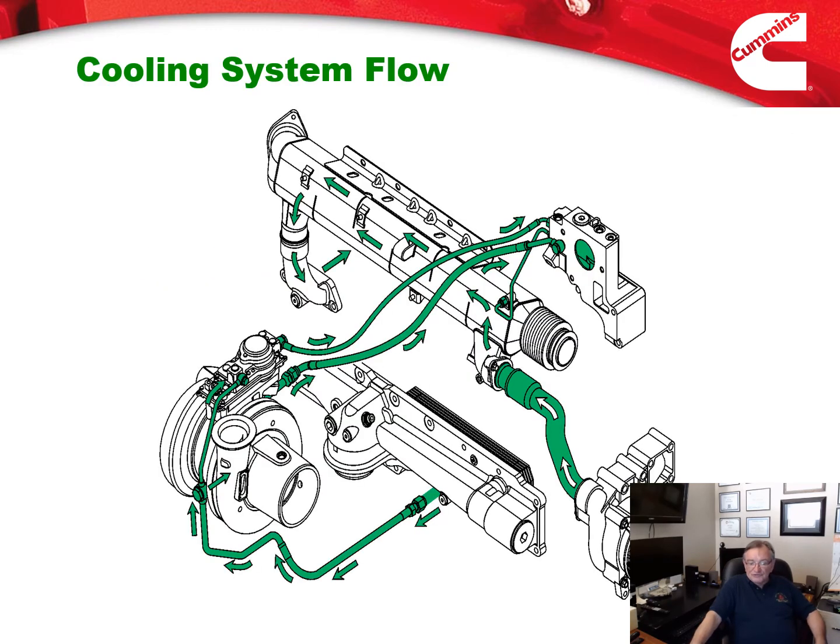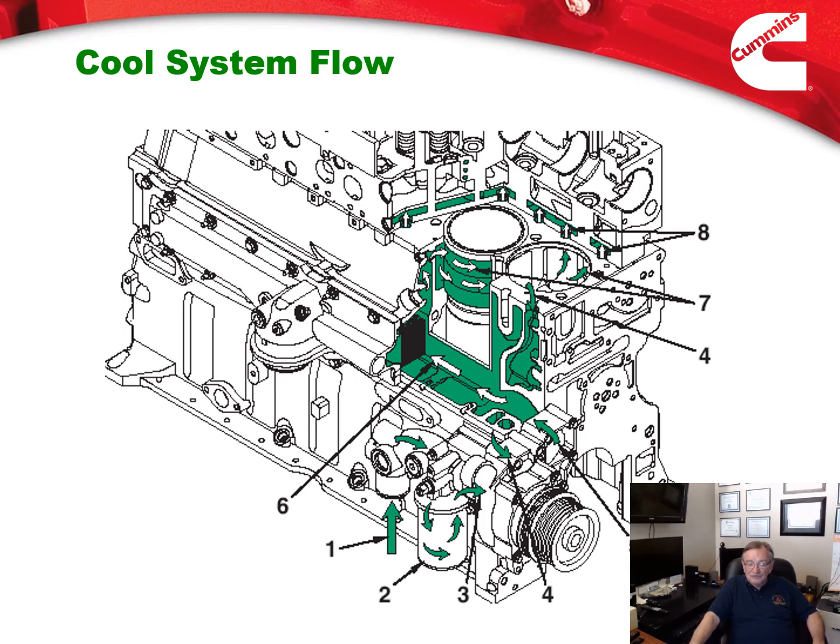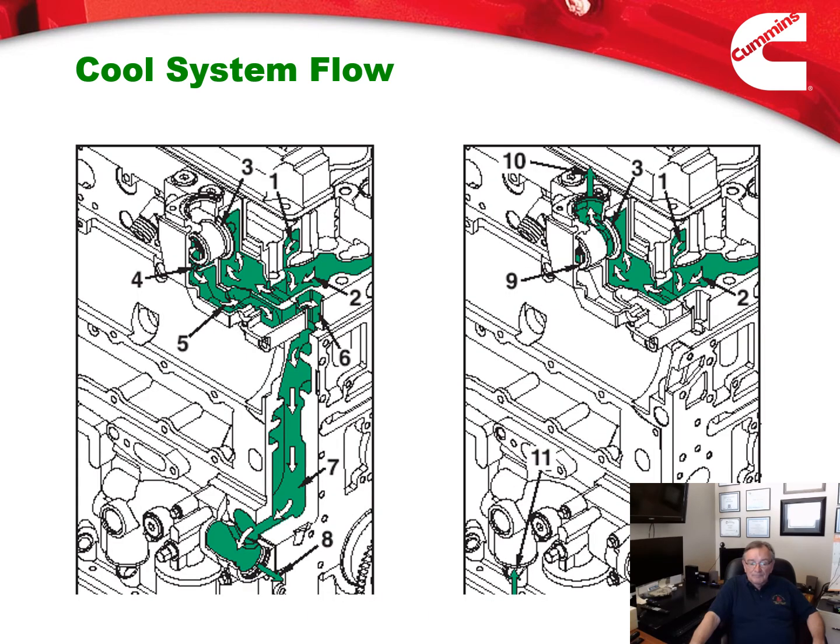It's showing the cooling system flow. Here it's going from the water pump. It's traveling through the EGR cooler, the turbo and an oil cooler, and through a plate behind the ECM. Here it's showing it traveling through the engine block, around the liners and also through the cylinder head. The injector cups have coolant flowing behind them. They're showing this here with the injectors, and the fuel system is part of the cooling circuit.